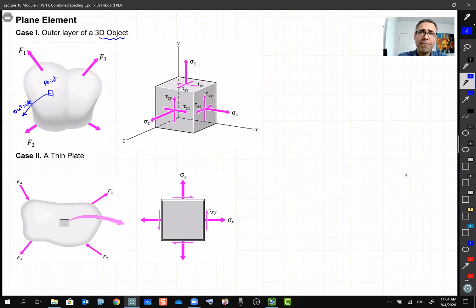So what do we have outside? Outside is just air. Nothing else, no force, nothing, right? If there is nothing outside, there is nothing compressing this cube on this surface, nothing to rub it, like sliding something on top of it, then it's safe to say that all the stresses on this side are 0.